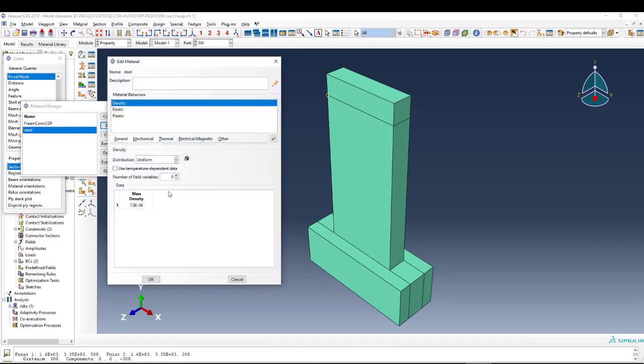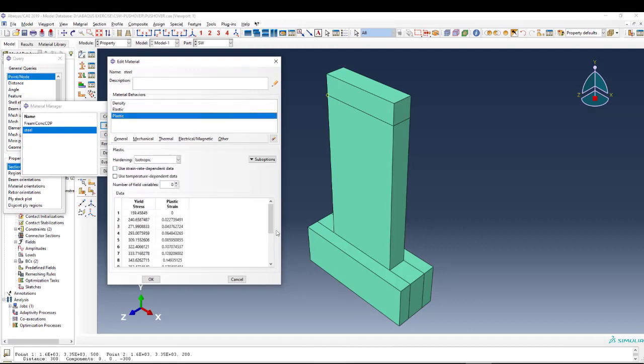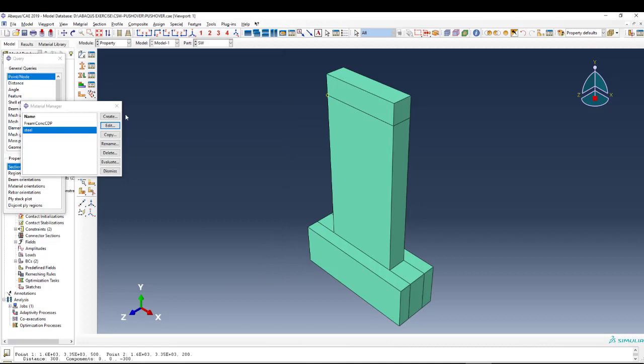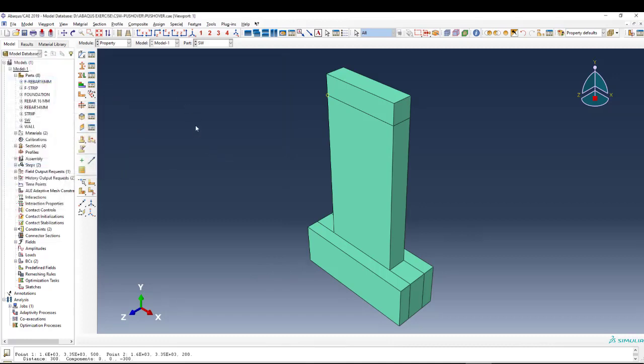For rebar we used this material, which is part of experimental data. The yield strength is about 160 megapascal at 0 plastic strain. The final is about 36% plastic strain, with a maximum ultimate strength of 400 megapascal. So how can we model this?